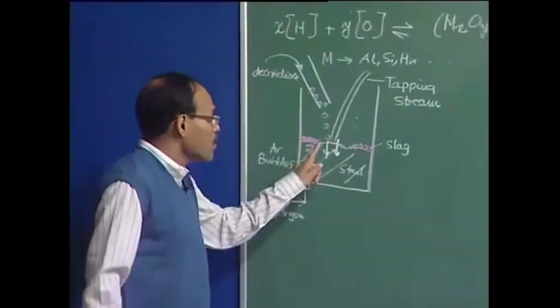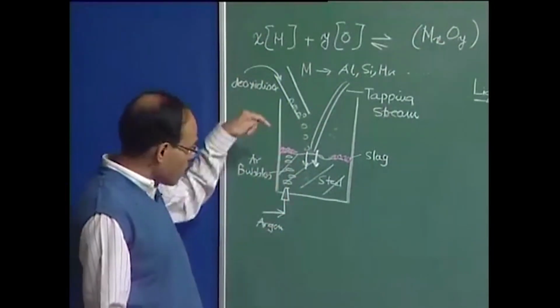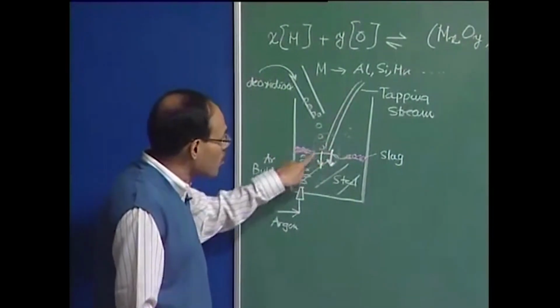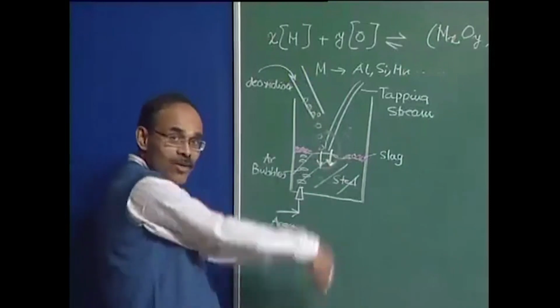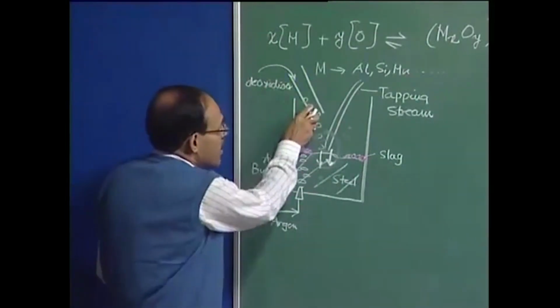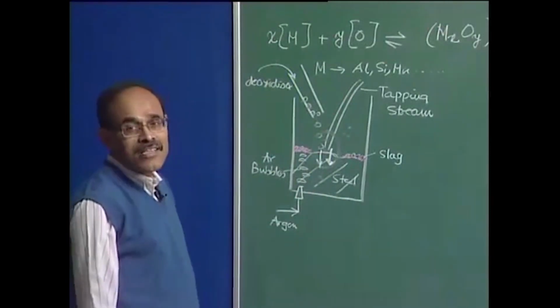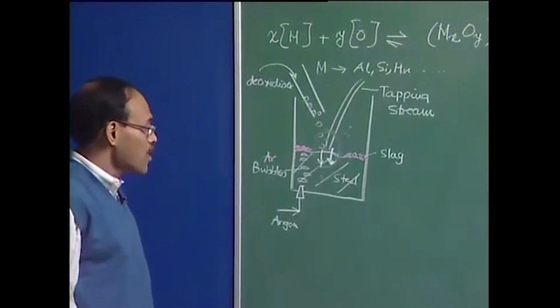And the most important site as far as their entrainment or their motion in the subsurface is concerned is the region close to the impinging jet, where you have the largest downward motion of liquid steel. If these additions can be caught in this particular region, then they have the potential to spend substantially longer time under the bath, and their efficiency of utilization is going to be larger.